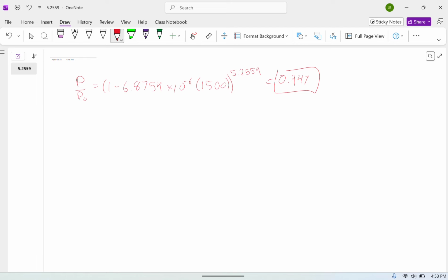So we're starting with the mixing. For this example, we will assume that we need a total supply flow of 6,000 CFM. This would come from our load calculations. And our outdoor air calculations tell us that we need 1,500 CFM. Again, these would be done with other calculations that are out of the scope of this video, so we're just going to assume that these were done elsewhere. So if we have 6,000 supply and 1,500 outdoor air, that means our return airflow is going to be 4,500. So these are our airflow values.